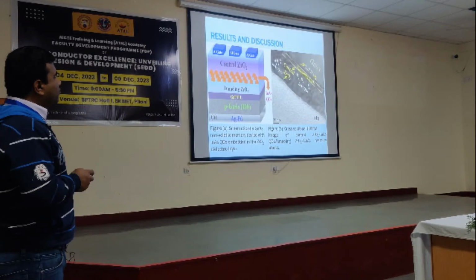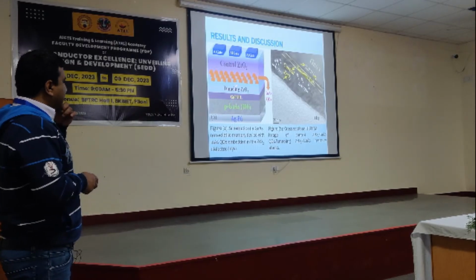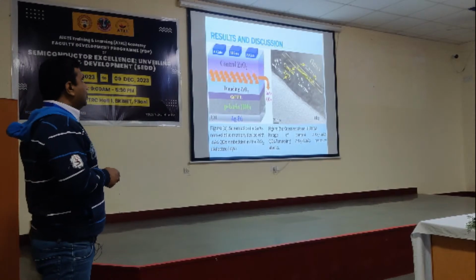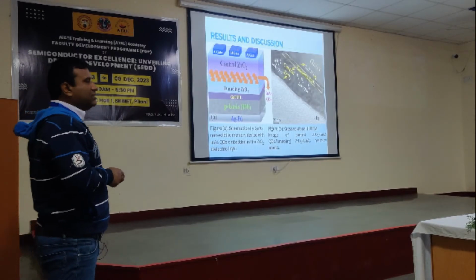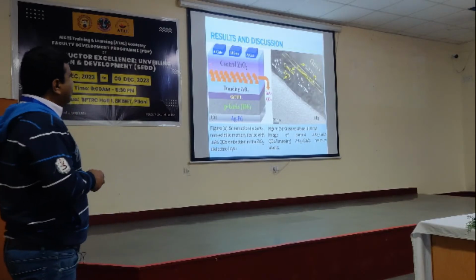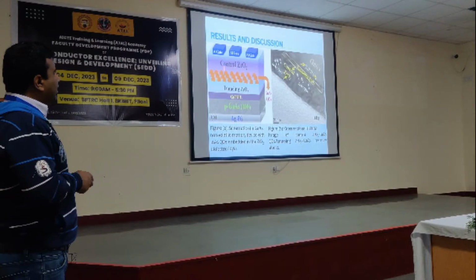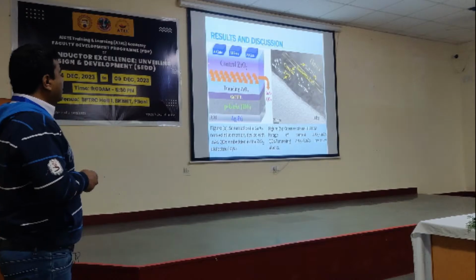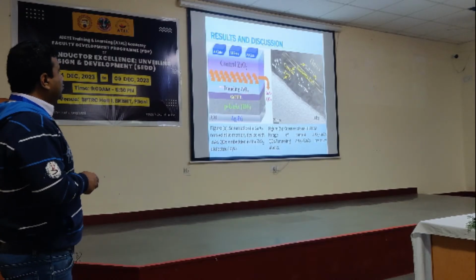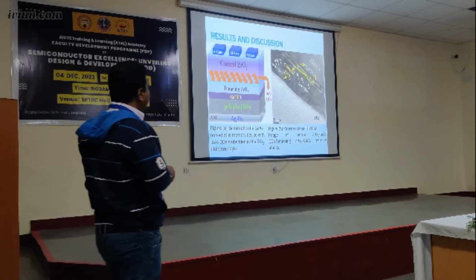Because if you are putting the bias potential on two sides, it is to minimize the leakage current, so that electrons cannot escape into this region, because here electron storage is taking place. The deposition of this layer ensures that the electron leakage current will be minimized. That's why the control ZrO2 thickness is much greater than this one. This is in the range of 5 nanometers, and this is in the range of 23 nanometers, right?